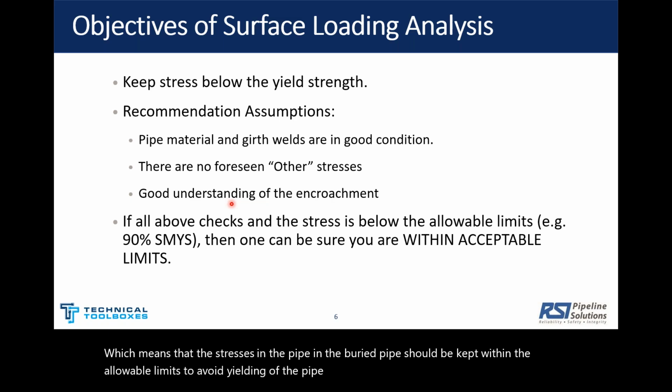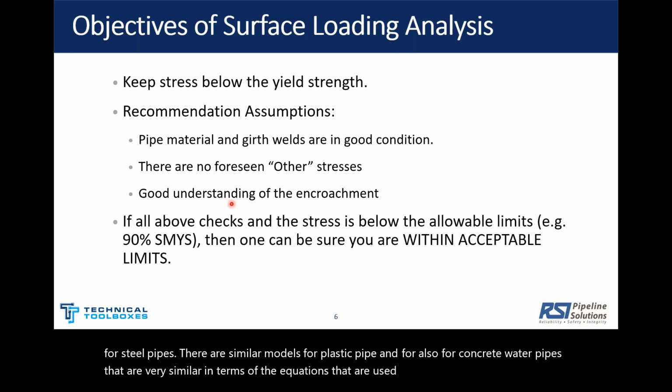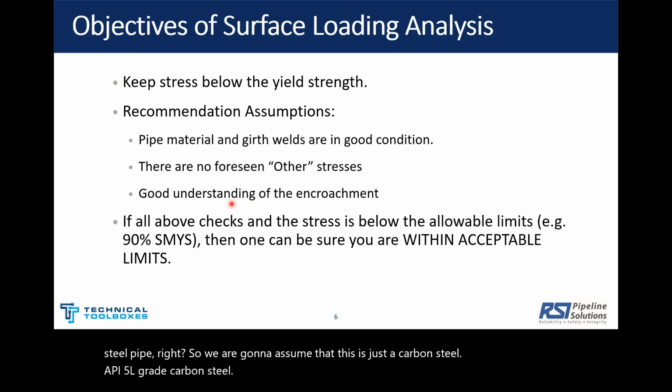The CEPA model is used mainly for steel pipes. There are similar models for plastic pipe and for concrete water pipes that are very similar in terms of the equations used, but CEPA is just for steel pipe. So we are going to assume this is carbon steel, API 5L grade or similar material.